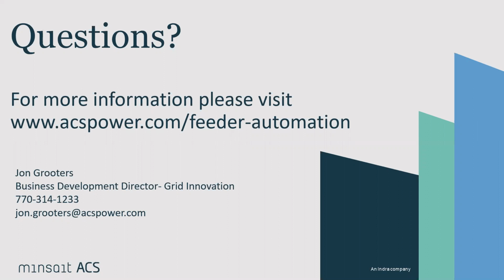So loss of communications is certainly something we want to make sure we avoid any incorrect switching actions. So if we do in fact lose communications to a device that's part of an active automation scheme, we will disable the FLISR application and automation for that particular circuit.